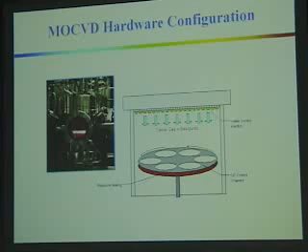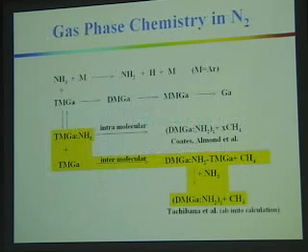Okay. Here is a typical Emcore type reactor. It's a rotating disc. We have flow down and out, very uniform mass transfer except for the boundary or the edges. The metal organic, for example, trimethylgallium, is mixed with ammonia in an injector head, and actually they have to be mixed at the right point because there's an adduct formation that occurs. These are then impinged onto this heated substrate, and the reaction of trimethylgallium with ammonia to give gallium nitride occurs on the surface. That's a simplistic view of what's going on.